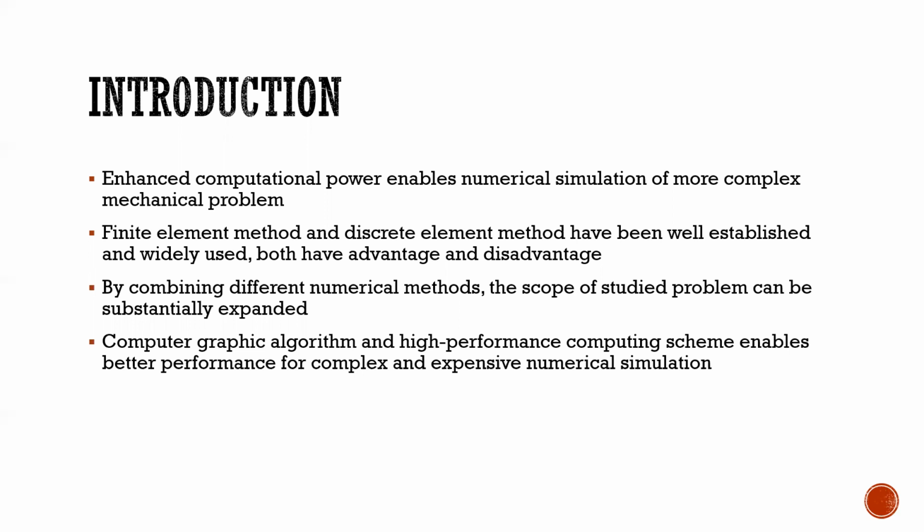For example, finite element method is relatively cheap to use and it's widely used. Most of the time, it could give accurate results, but it does have limitations. It has a continuum assumption, which means with finite element method, it's pretty hard to simulate the fracture of a material. On the other hand, discrete element method does not have this limitation. But in order to simulate the material, you need a really large amount of particles, which is expensive.